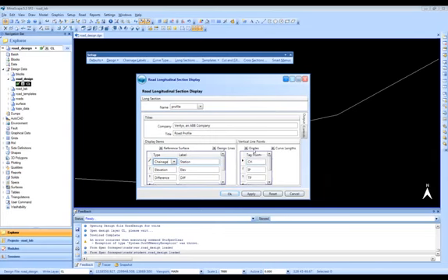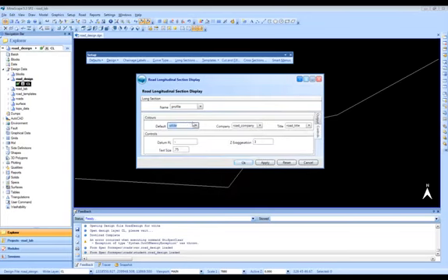The other thing also, vertical line points. Again, what do you want to see in that vertical alignment profile? And again, various tag points here, very similar to what we've shown before, but you can pick and choose what items you do want to see, and have those listed here. On the control tabs, again, just some information about how you want this to appear: text size, the exaggeration if you want some of that, what colors you want on there, and so forth. So again, these are just display definitions that you might have created.